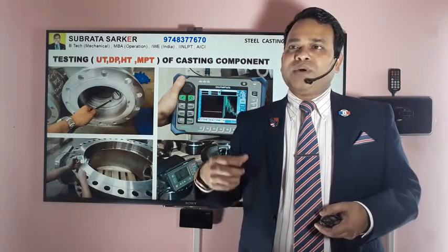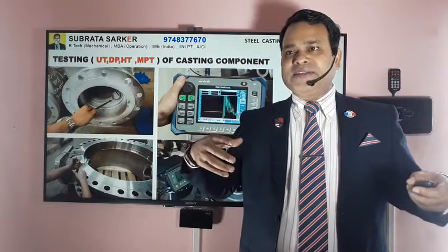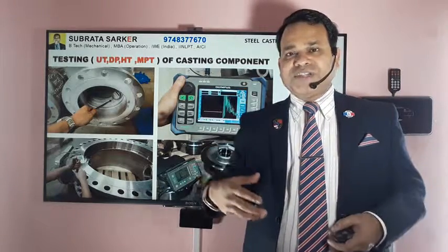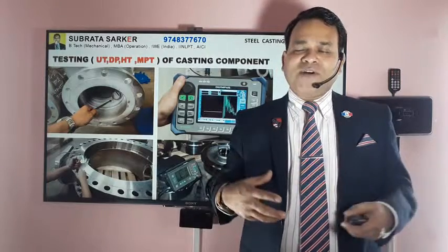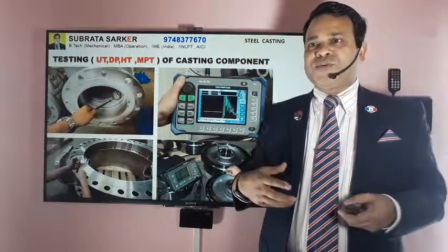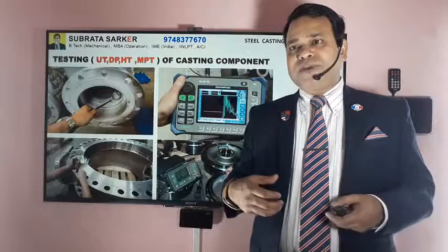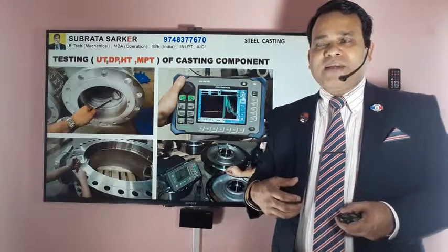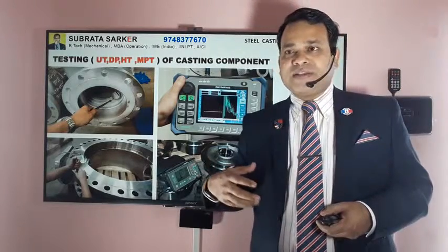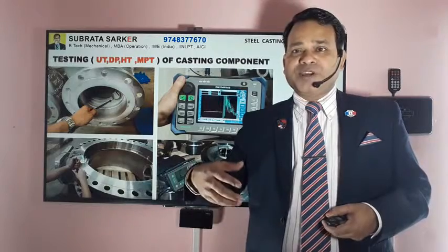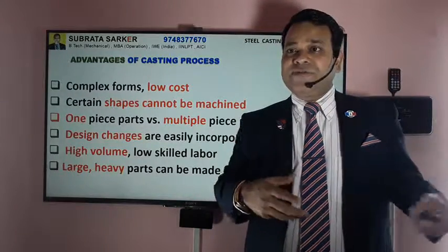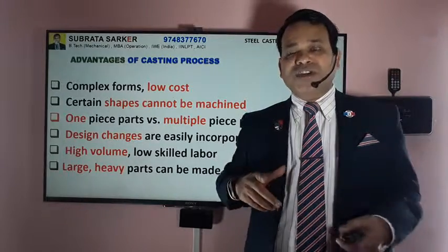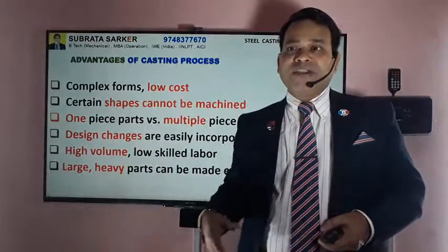And in many cases there are design changes, and it is easy to implement a change in the pattern. If high volume is needed, casting is also very suitable. And large and heavy parts are in some cases easier to manufacture by the casting process than by fabrication, because a lot of distortion comes if the component is much bigger in the fabrication process.